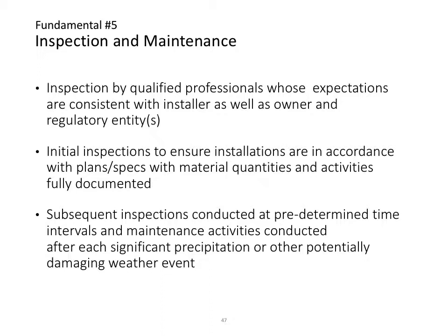You want to be there to ensure everything's done properly. And then something else to keep in mind: out here, the site's covered in snow, you can't get up there every 3 to 6 months, but make provisions for periodic inspections to make sure you're getting the growth and the erosion control that you're looking for on these sites. And if there's a really bad weather event, maybe not a bad idea to send someone out there to take a look and see how the site's holding up.